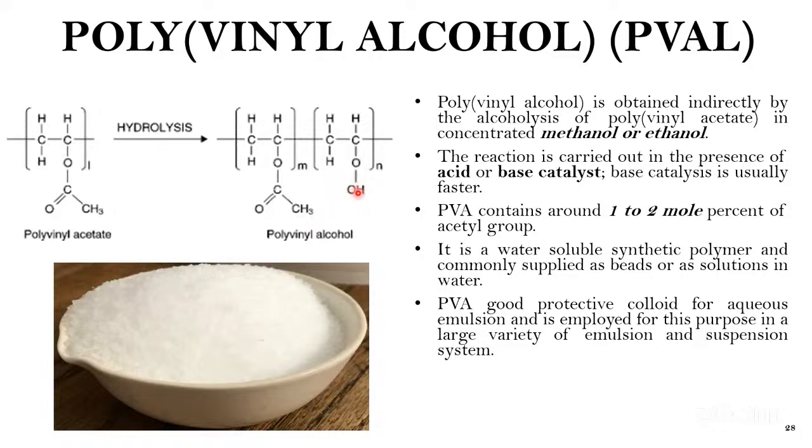This alcohol group makes a hydrogen bond with your water, and that hydrogen bond is quite weak compared to the bonding within the polyvinyl alcohol. That is a very different concept we study, known as cohesive energy density. If you know cohesive energy density well, it is very easy to predict which polymer will dissolve in which particular solvent.